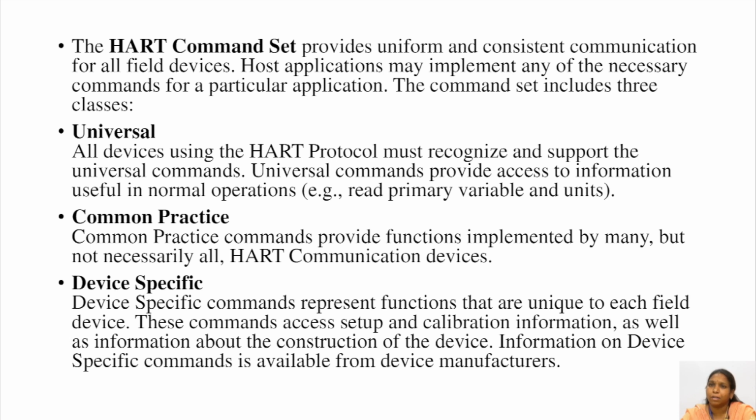Common practice commands provide functions implemented by many but not necessarily all HART communication devices. Device specific commands represent the functions that are unique to each field device. These commands access setup and calibration information as well as information about the construction of the device. Information on these device specific commands is available from the device manufacturers.